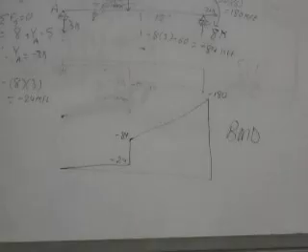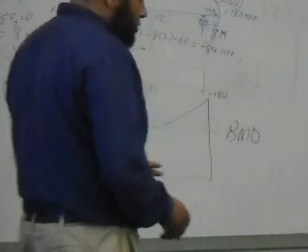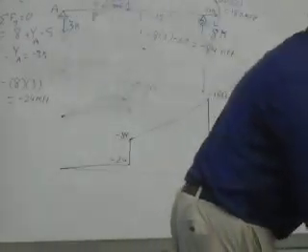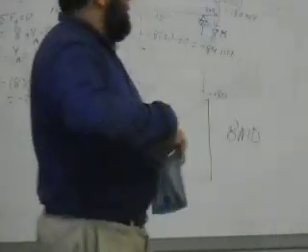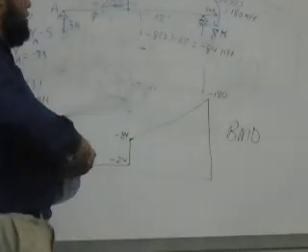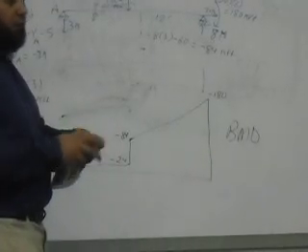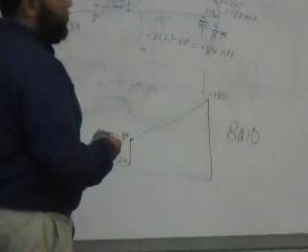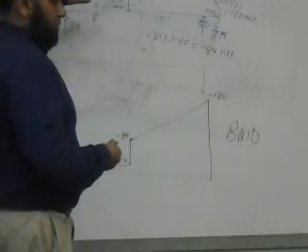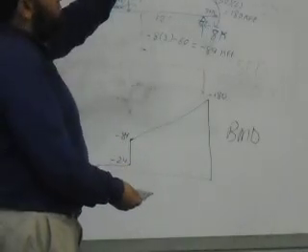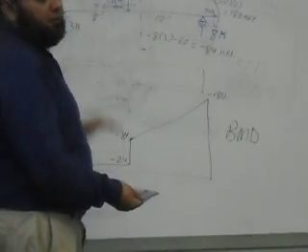If this is a reinforced concrete beam carrying only negative moment, you want the main reinforcement to be upper reinforcement. So, if I draw a cross section of the beam, the steel bars will be up, not down.